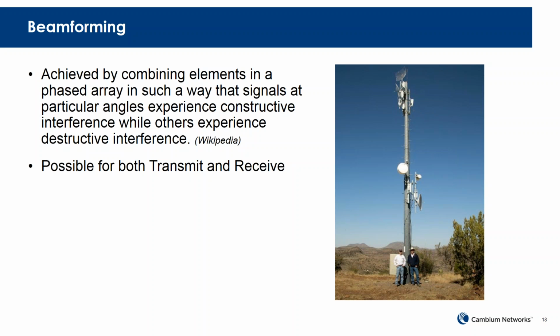And so the points that we're going to talk about are this idea of a phased array, and then constructive interference and destructive interference. Constructive interference is when we intend that 2 signals combine together and reinforce each other and become stronger. If you remember the sine waves in wireless, when those are aligned and you combine them together, it makes the amplitude of the signal louder. Destructive is when they're out of phase with each other and you combine them. You actually get what I'm going to call a canceling effect, almost like noise canceling headphones in a sense.